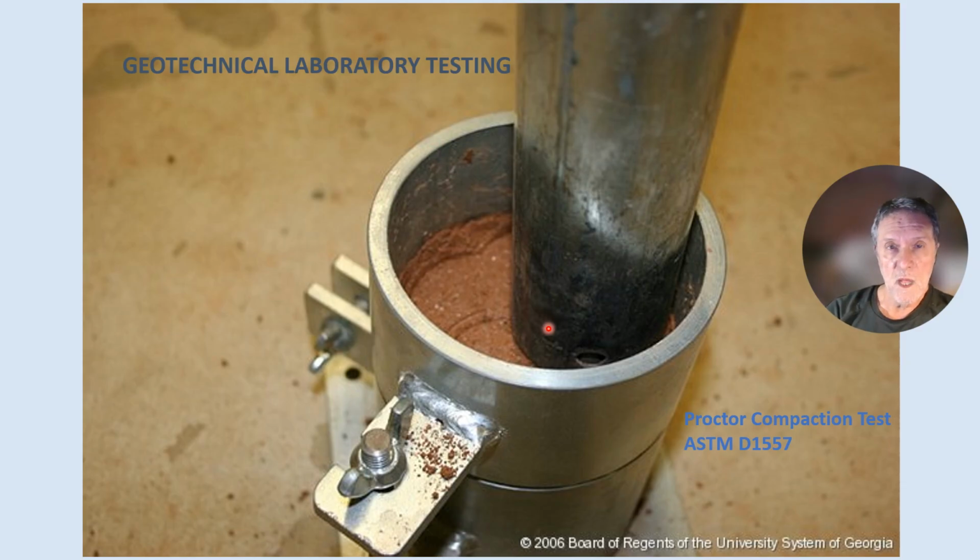And you do this, I was trained to do it in 5 lifts or 5 layers. Each layer was pounded 25 times by this weight here. I forget the actual weight of the weight, but each layer is 25 times, and you bring it up, bring it up, bring it up, and then you come out with a molded, compacted cylinder of soil, and you weigh that and determine its moisture and determine its density.